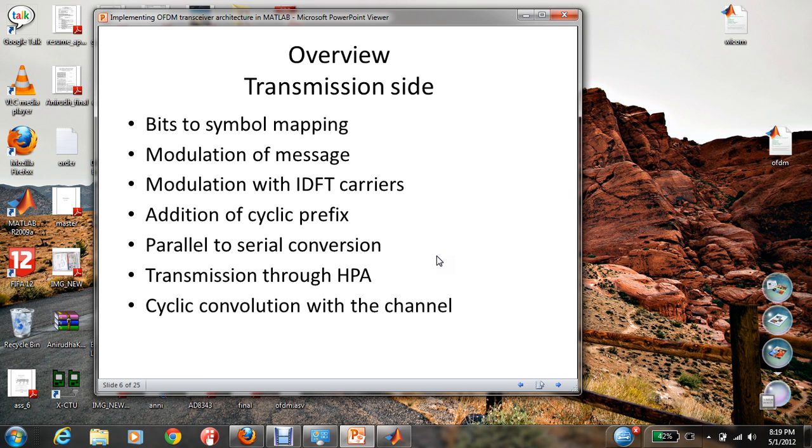This last L minus 1 symbols will interfere with the next set of m plus L minus 1 symbols, because as a result of multipath, another set of m symbols will be observed that will again be convolved with the channel response of length L, giving again m plus L minus 1 samples. So the last L minus 1 will interfere with the next set of received data. This causes adjacent block interference, which is unwanted.